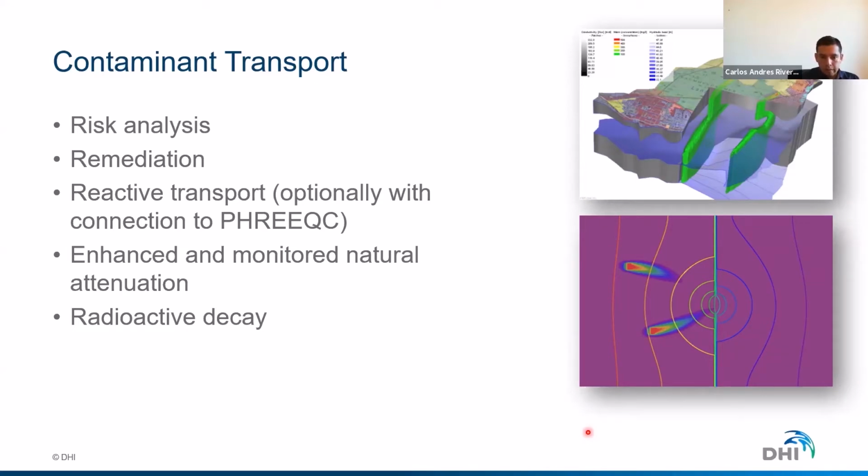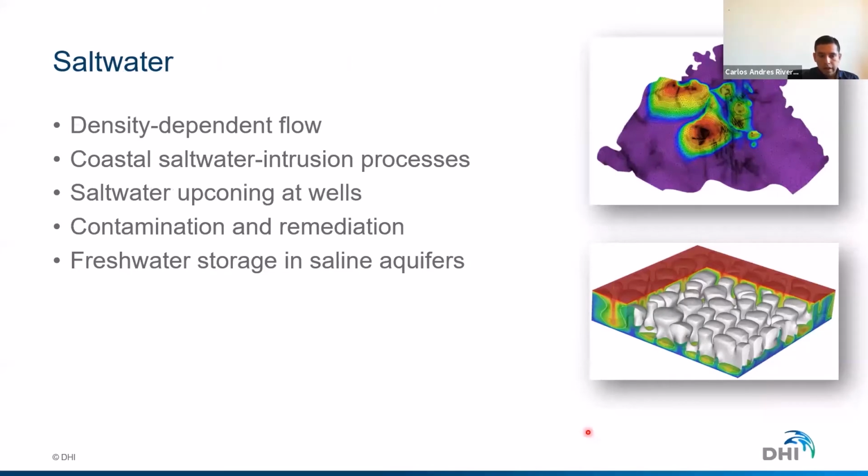We have the possibility to solve reactive transport in FEFLOW or use other software like PHREEQC. We can do reactive decay; cases of uranium mines, for example, or other radionuclides can be easily simulated in FEFLOW. Saltwater density-dependent flow. Again, an example in Australia, I will show you in just a minute. Cases of coastal saltwater intrusion, saltwater upconing of wells, contamination and remediation. You have aquifers for freshwater storage in saline aquifers.